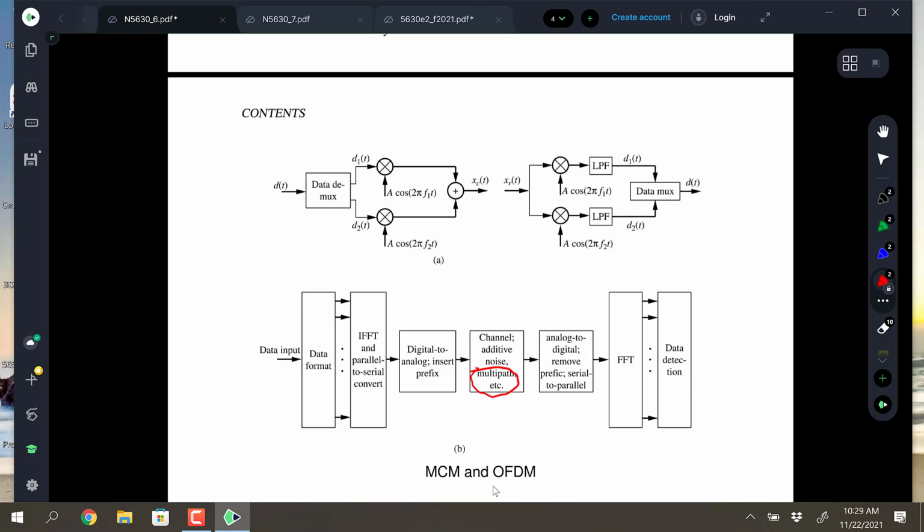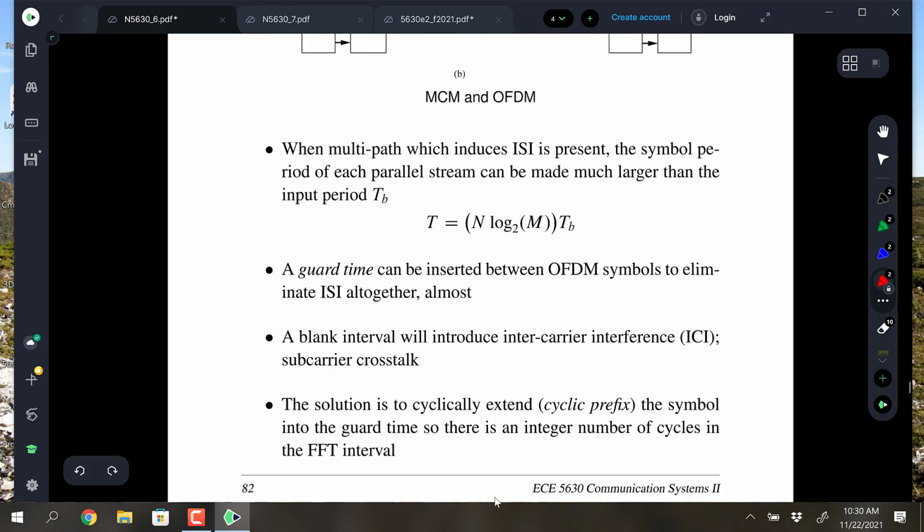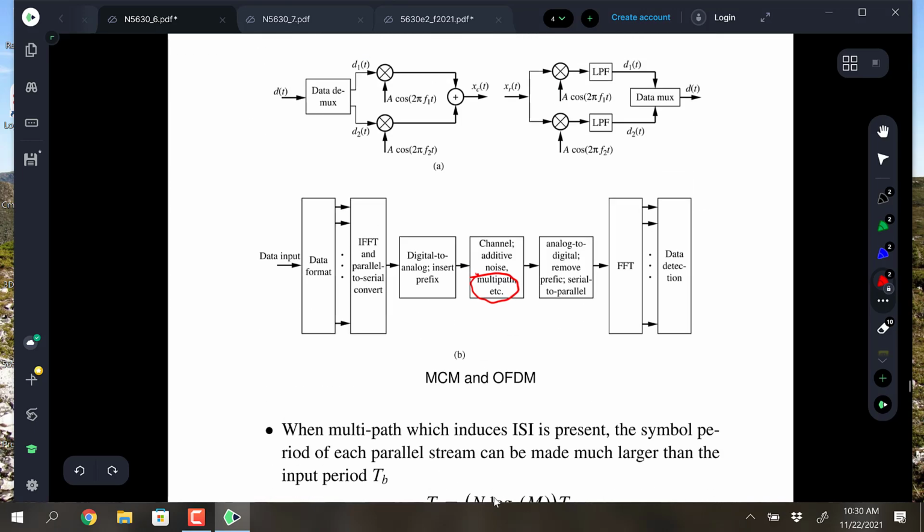So typically they put QAM, binary, quaternary, 16-ary, whatever, QAM on at the transmitter. It gets converted to the time domain and sent as a time domain waveform, and then it gets transformed back to the frequency domain, and each of those carriers comes out and contains a serial bit stream that would be for that particular channel. You said QAM on each individual bin? Yes, yeah.